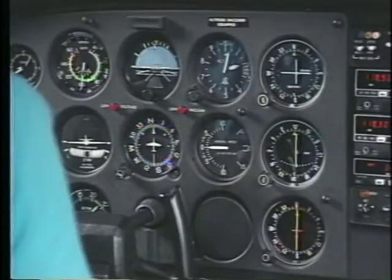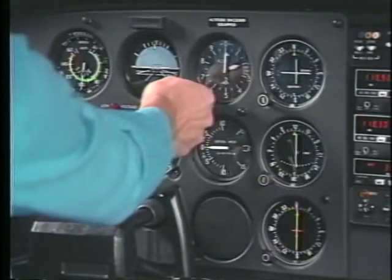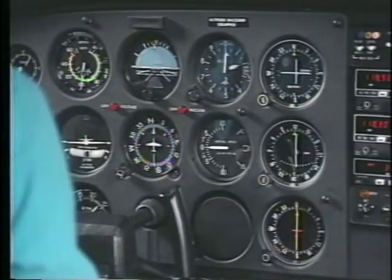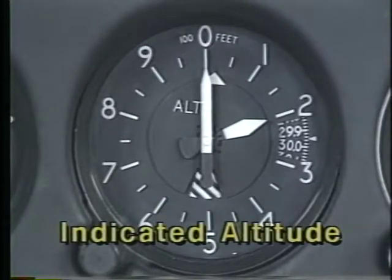The best way to minimize this type of error is to periodically reset your altimeter to the current setting as reported by the nearest FAA facility. Keep in mind that an altimeter measures altitude above a specific reference. There are various types of altitudes depending on which reference you are using. For example, indicated altitude is read directly from the instrument.